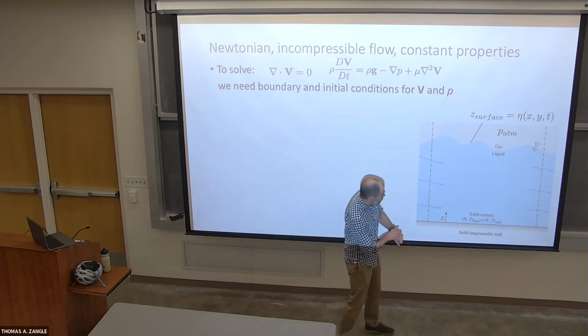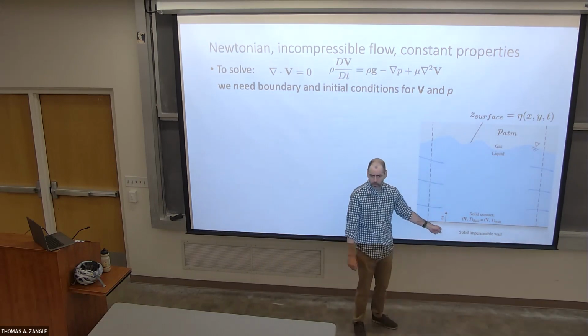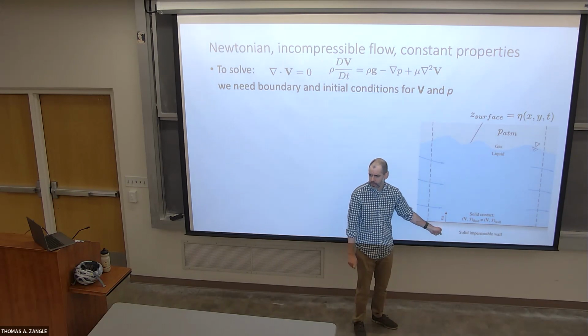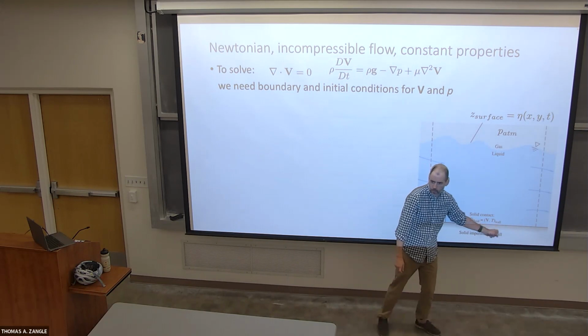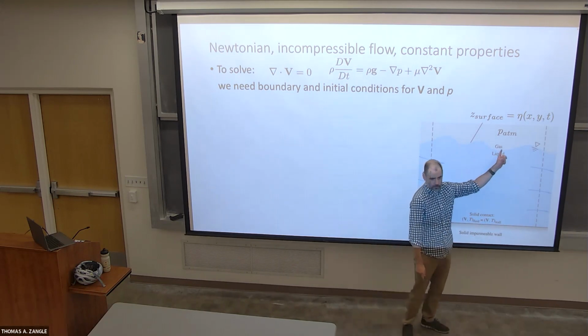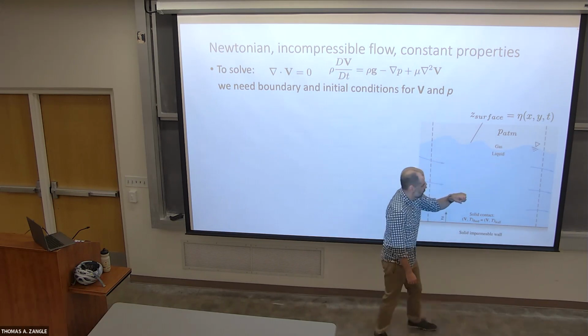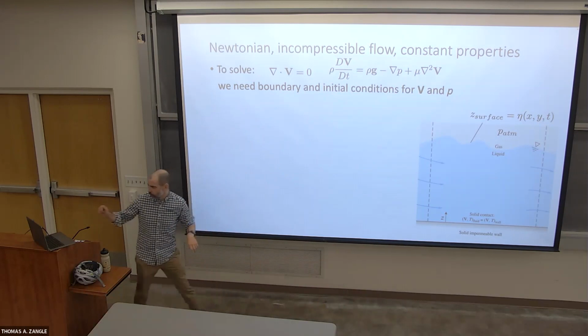Because in general, if you think about it, we discuss what happens on a wall, right? So on a wall, or a solid surface, we have a no slip condition, meaning the velocity of the fluid equals the velocity of the wall. But we can also have, for example, the interface between a liquid and a gas. And for general flow, inflow and outflow boundary conditions, as well.